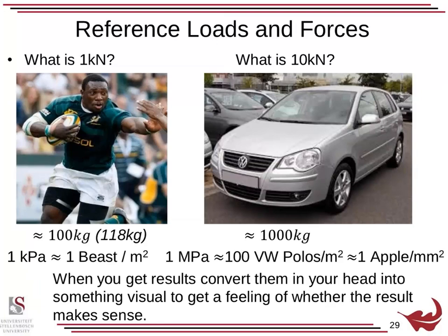So, all along I've been talking a lot about reference loads, and what I find students often make mistakes with is that they will get to an answer and they don't really have a feeling of, is that a big load or a small load, or does it make sense? What is useful is to have some reference loads in the back of your mind, and when you calculate a load of 1,000 kilonewtons, what is that? Well, firstly, what is 1 kilonewton? That is one big rugby player per square meter. So 1 kPa is 1 beast per square meter.